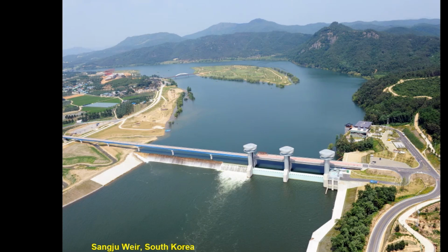And this is the weir, Sangju, after construction. You see a little powerhouse here, right? So micro turbines here. You see 2 major floodgates. Of course, you want to get the main floodgates on the outside of the bend and make sure that you don't get silting at the intake of your powerhouse, a problem that Professor Ettema dealt with in great detail in the past couple of days. Little flood control here, so extra weirs, and then you have a little fish passage that goes left and right here on the right bank of the river.